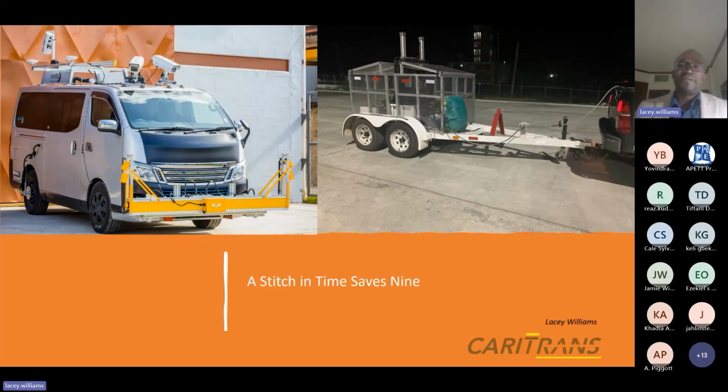The way this piece of equipment works is, you see the pistons at the top, it drops a known load from a known height, and the impulse that is generated is picked up by geophones on a rail at set distances. Based on the deflections, you then know how stiff or how strong the various sublayers are.